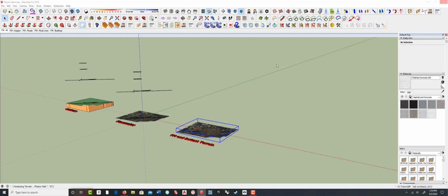And as you saw before, it actually kind of ends up dropping itself right in over top of the other terrain. So if I was smart, I would have set a new layer. If you create a new layer and make that the active layer, when it creates this new shape, it will be on that layer so you can turn it off and on. I'm just going to select it and cut it, delete the other one, and paste it back in place.